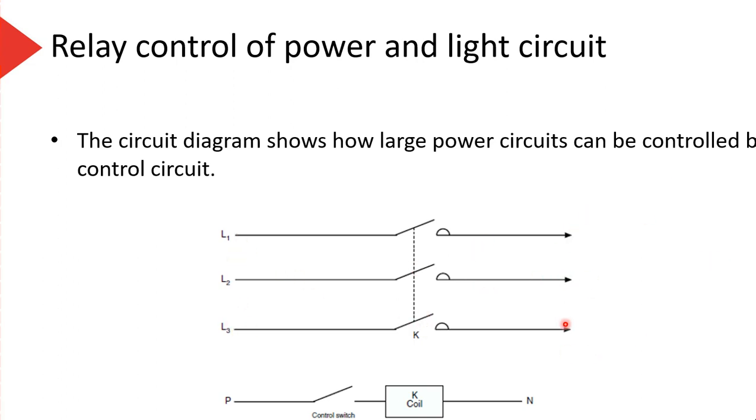We then have power off these three branches, which might go to a motor or whatever. This is how our stop button circuit of 402 works. Down here where it says control switch, that's all our emergency stop buttons. They can kill power to this coil, and then off these wires here would be all of our sockets in that room. So when this is on, the sockets have power. When the coil is de-energized, all of these switches open and the sockets no longer have power.